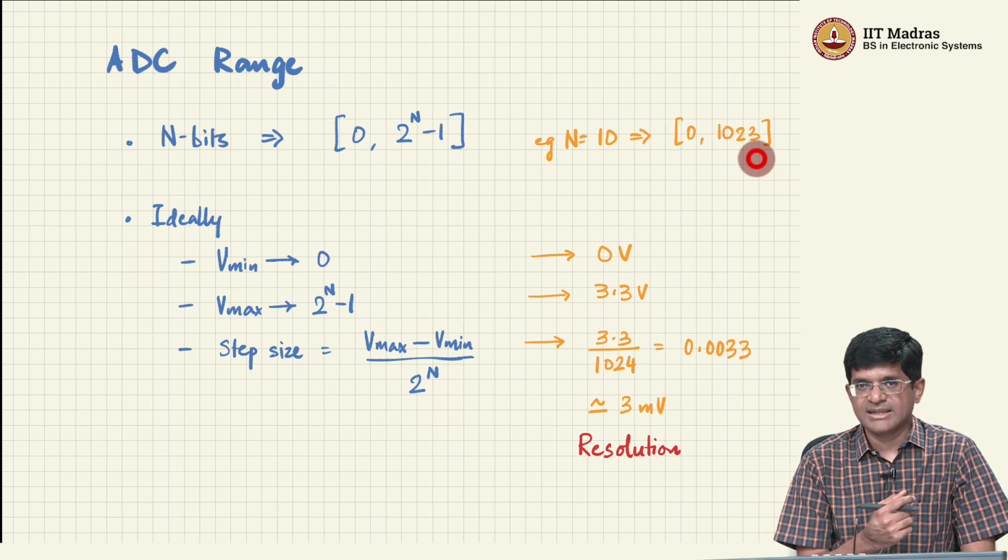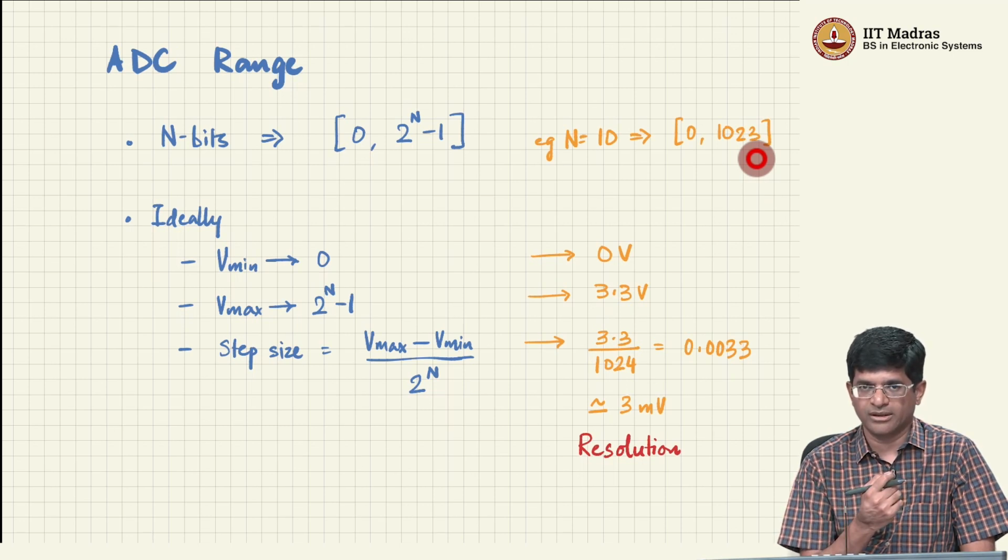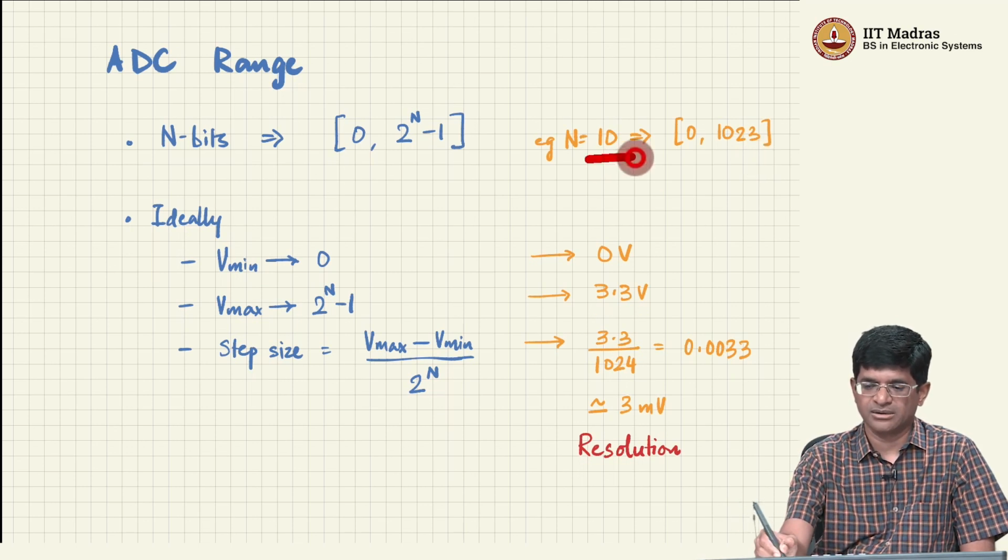What that implies is that if I was trying to measure, let's say, some electrical signal in the brain or a muscle potential, this is probably not good enough, because you are talking about microvolts over there. But then the problem that arises is whether this is even the right application, because microvolt kinds of voltages have other problems. It's not just an issue of, hey, maybe I need n equal to 20.